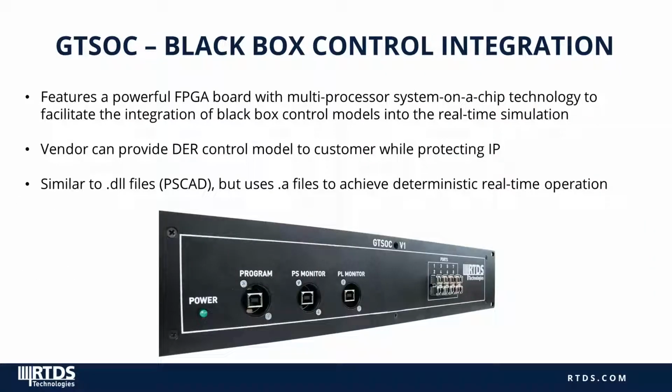So this is the GTSoC. This is the recent development at RTDS for the black box control modeling that I mentioned. It's a rack-mounted unit that can be added to the RTDS Simulator. It features a powerful FPGA board with multiprocessor system-on-a-chip technology. So the ARM cores on this board allow for vendor controls to run in real time as part of the real-time simulation, while remaining black-boxed, protecting vendor IP. The GTSoC runs static .a library files, which contain the controller source code, whereas offline tools like PSCAD would use DLL files, which the audience might be familiar with.